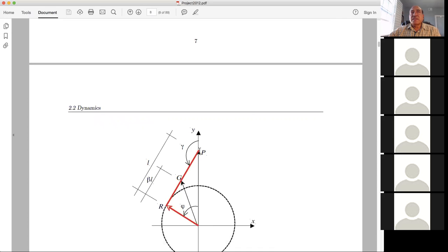So there's a cylinder around point B, pushing on the connecting rod sideways, and from the top there's a pressure coming down. The connecting rod now has to take the pressure force, which is coming down to point P, and some side forces. The side force is coming from the cylinder, because if there's a little tilt on the cylinder, then there's going to be some side forces on point B.